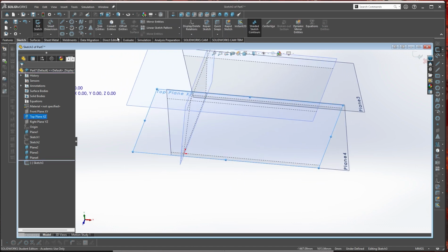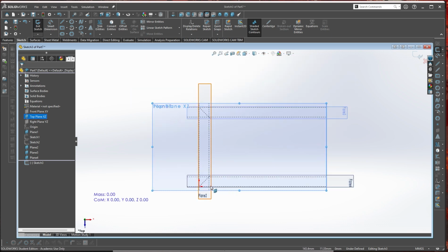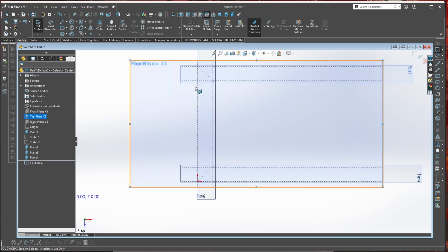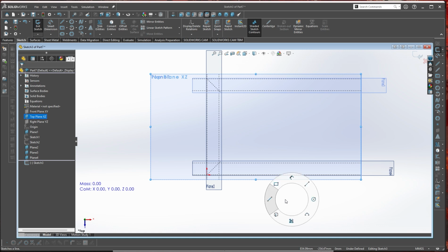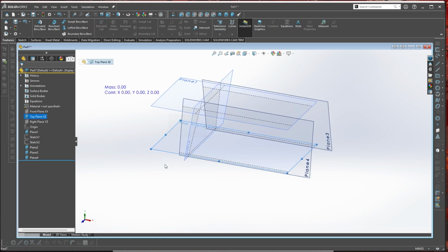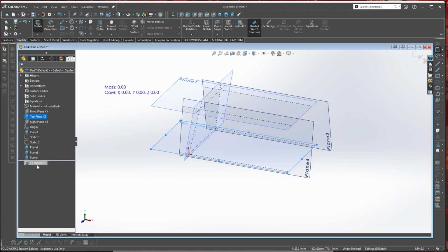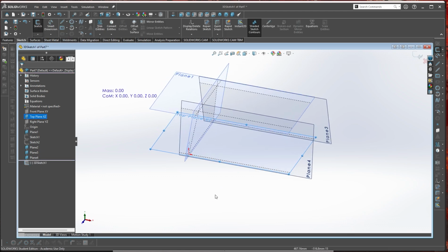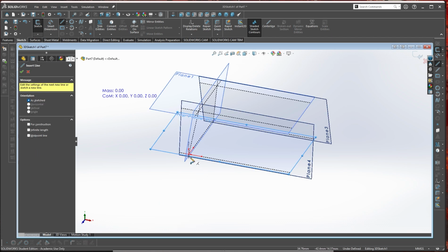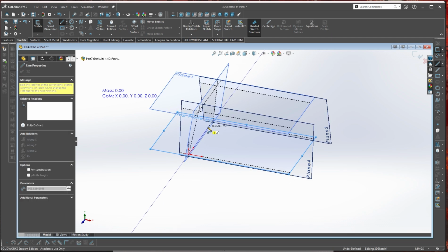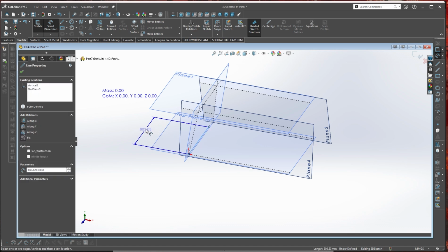Let's start that sketch up, and move it from the top. Let's take our top view, and we're going to start on the origin and then go out from there. So we'll start the 3D sketch right here. Under Weldments, you can just select the 3D sketch right there. Make sure you're in 3D sketch before you start, otherwise you're going to have to come back and do this, or you do two different sketches, kind of the same at this point. Let's go ahead and drop that into place.